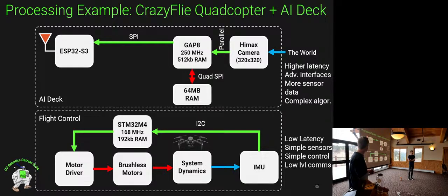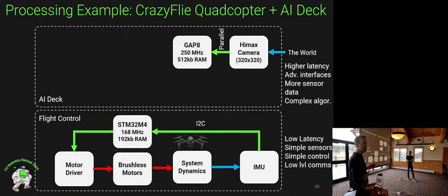Speed of the bus, I think it's probably in the order of 50 to 100 megahertz. But it's a quad bus, a quad SPI bus. Most people have probably worked with SPI buses, but a quad SPI is just four lanes of data as opposed to one. So at a 50 megahertz rate, you're getting 4x the data transmitted across. It's just way quicker. You can transmit megabytes of data across this bus, which would allow you to get real time access to this memory for processing. So that's kind of cool.